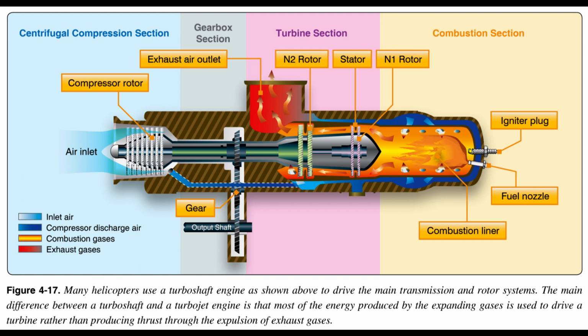Main rotor transmission. The primary purpose of the main rotor transmission is to reduce engine output RPM to optimum rotor RPM. This reduction is different for the various helicopters. As an example, suppose the engine RPM of a specific helicopter is 2,700. A rotor speed of 450 RPM would require a 6:1 reduction. A 9:1 reduction would mean the rotor would turn at 300 RPM.